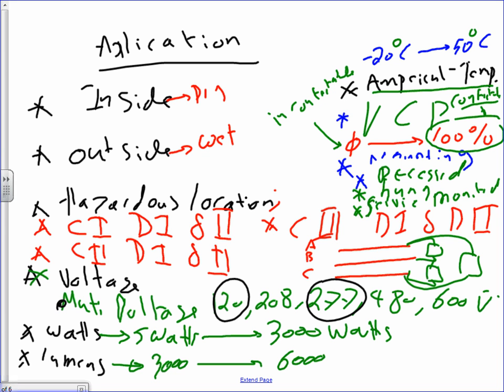That's why it's 277. A lot of commercial and industrial buildings, guys, burn their lights at 277. Why is 277 so convenient? First, it's low enough to be safe and high enough to be efficient, compared to the 480 and the 600.